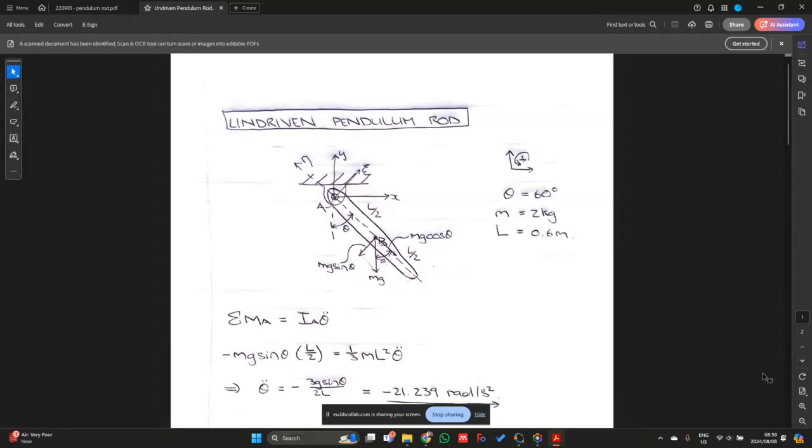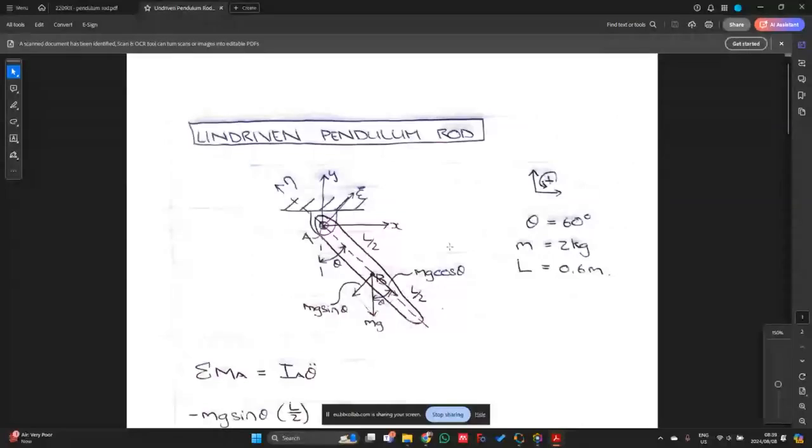Okay, so then we just want to perform some initial or preliminary calculations as well that we can later on use for sanity checks. So in this case, I decided to place the psi eta coordinate system over here. I could have also placed it at the center of mass. It doesn't really matter for this initial calculation that I'm going to do. I just want to relate the forces that I calculate over here to the X and Y components. Once I have that in place, then I can use that to check the reaction forces that I'm going to get at the end. Okay, so it would be totally fine if you wanted to place psi eta over here as well as we had with the original schematic.